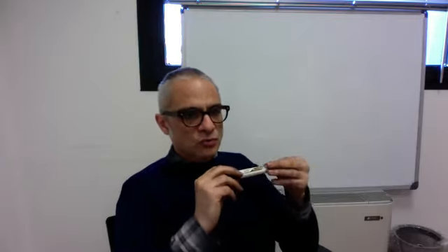Now, in what people sometimes call acoustic media, like gases or fluids, the surface forces are always directed perpendicular to the surface that I'm talking about. You take any surface within the medium, no matter how oriented, and you measure the forces that act on it. A fluid or a gas can be defined as a medium where those forces are perpendicular to that surface.